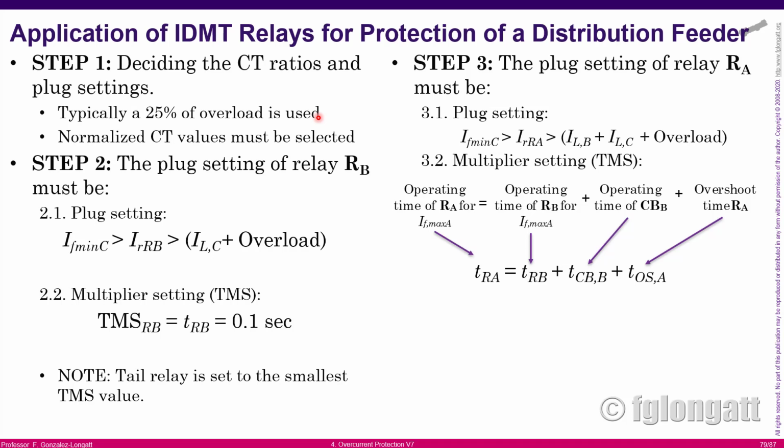People from the industry may say no, you are crazy. There is not a specific paper saying that, but it's a practice that can be done. I would like to clarify here: it's not defining the overload protection. It's defining the starting point of your overcurrent protection.